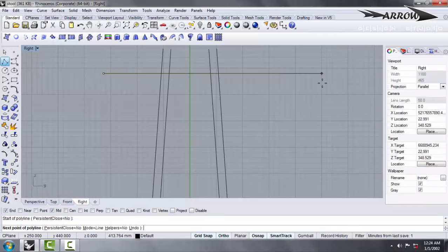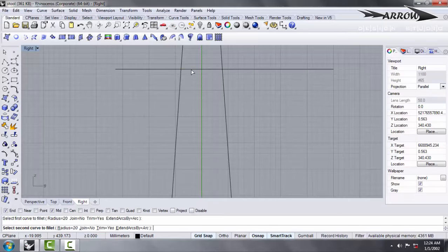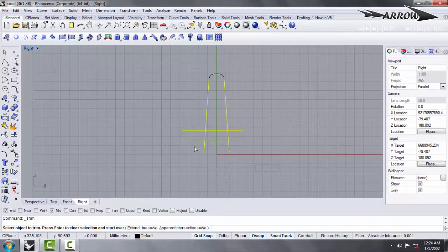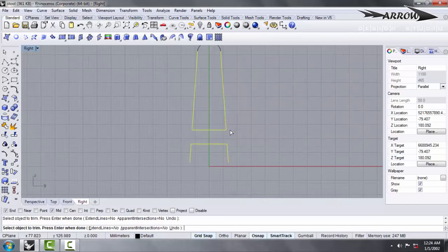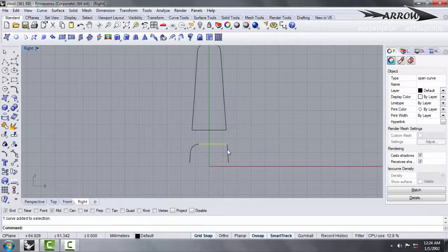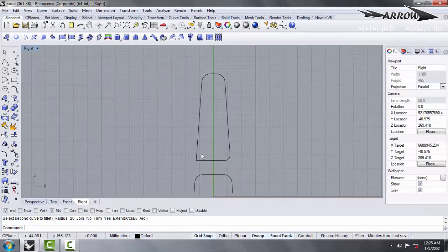No issues in that. So you can make it 15, and you can just make a lengthful curve over here and delete this one, and then say you delete these lines. So fillet, you just understand the crux of the matter, how I'm going to make it happen this way. Here trim, and you need to trim this one. Sorry, again I'm doing the same thing. So I'll trim this one, this one, this one, this one, and again I'll be saying filleting this one with this one, this one with this one,